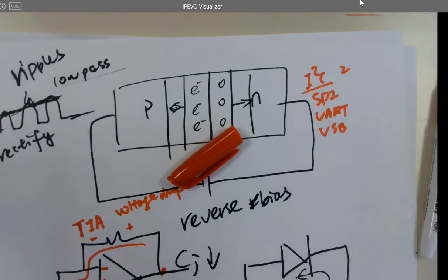Every rising edge is going to trigger one data in here, like 1 1 1 1 0 0 0 0. So I know it's F0. And the protocol understands that the first hex number is the address, followed by the data, right? If I'm writing to the follower, the first hex number is the address, and the following hex number is the data. So I'm going to write that data into that address in the follower. That's how different devices finish a very simple 1-byte communication.